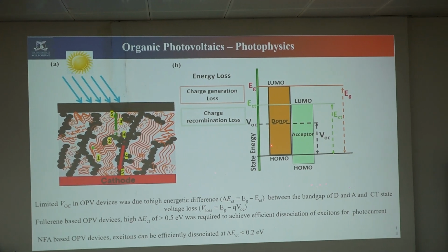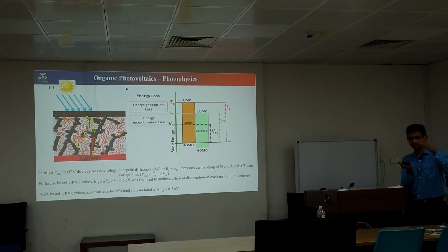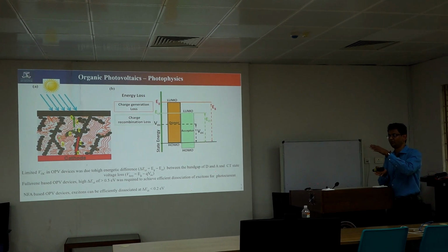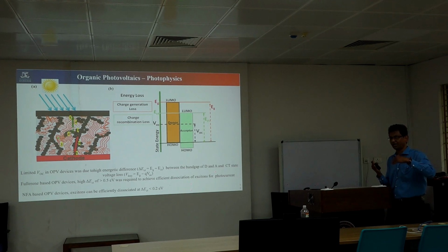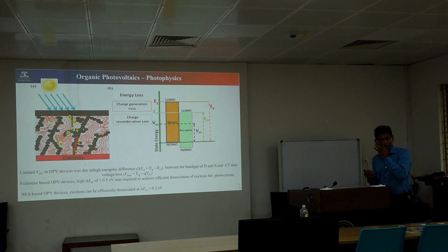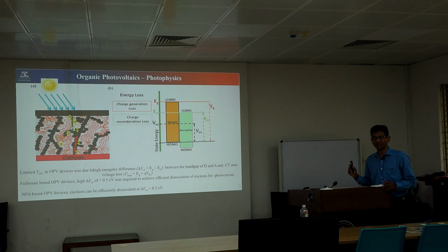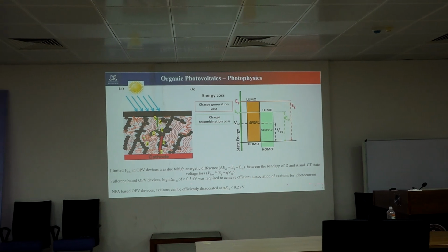So even at this maximum, we are losing a lot of energy. Energy in the sense I'm talking about is the voltage, the band gap. The band gap is also nothing but energy. Then light is absorbed only according to the band gap, because whatever the input light, its energy should be higher than this band gap. Then only can it excite an electron. If the energy is very low, it won't. Why is silicon only absorbing up to 1100? You know that because its band gap is 1.1. Yesterday I said 1.1, which is close to 1100. So it only absorbs up to 1100. Beyond that, the energy is too low to excite an electron. That's why we can't have any absorption at wavelengths longer than 1100. I'm talking about 1100 nanometers. So it all depends on the band gap of the material.